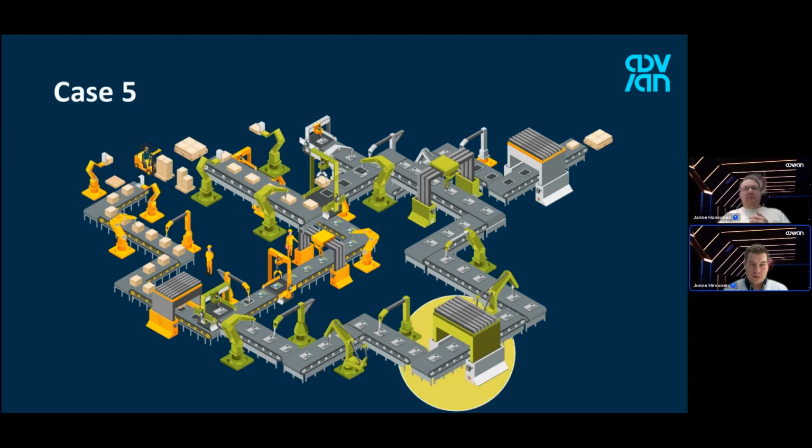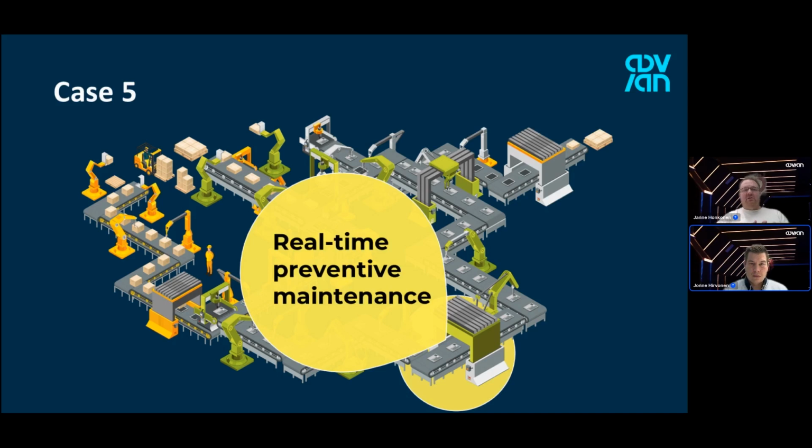Coming back to the bending machine, like any other machine, it has wearing parts that may cause slippage when we are bending the pipe. So by utilizing different sensors, we can identify the factors influencing the slippage, and we can predict the start of the slippage. So this enables condition-based maintenance instead of the traditional calendar-based one, which means the component is not replaced too early, nor too late.